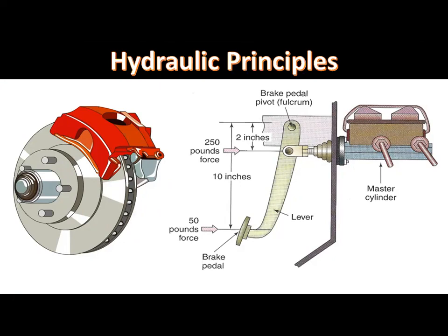One of the basic principles of hydraulics is that liquids are not compressible. A second principle of hydraulics used in brake systems is that pressure in a confined fluid is transmitted equally in all directions and acts with equal force on equal areas.